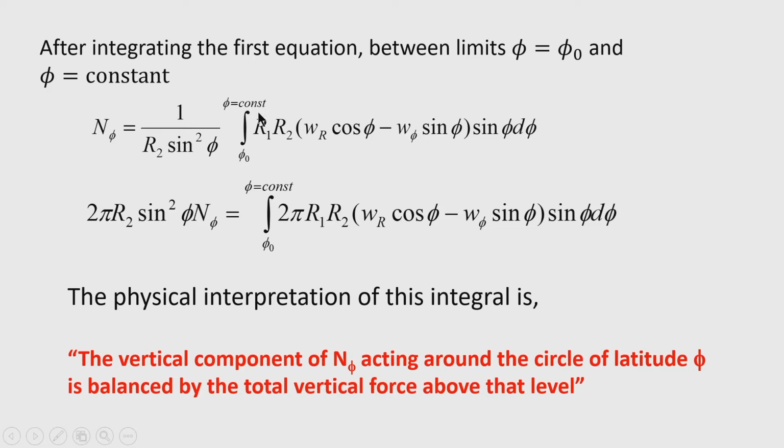So, when we take the definite integral of this equation, the constant term disappears. In between these limits, phi naught and phi as another angle, we can find the integral expression of this quantity, and therefore n phi is completely known. Given the geometry of the surface and the loading on the surface, we can obtain all the parameters, and ultimately after integration we can get n phi.